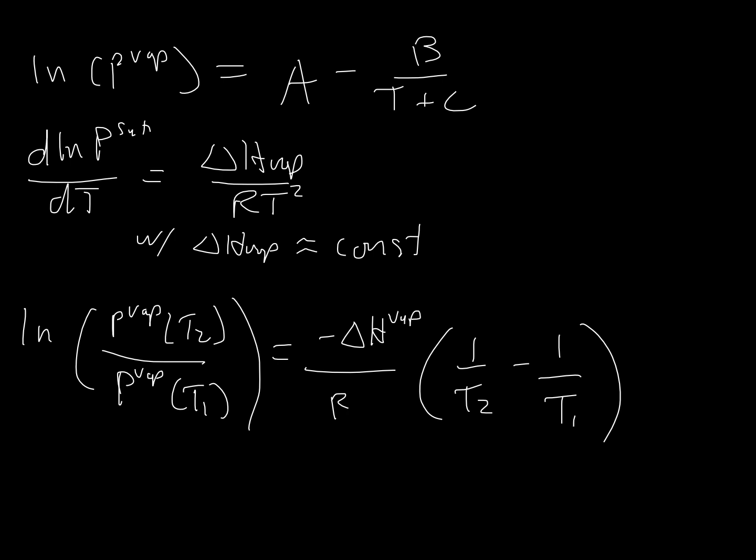which means that it's not the end of the world if you go a little bit outside of the correlation range that it lists in the book. For heat capacities, it's a big no-no. Do not go outside of the range because it is a dummy fit. It has no theory behind it. It's just a polynomial fit that seems to do the data well.